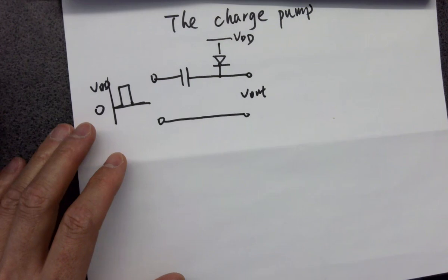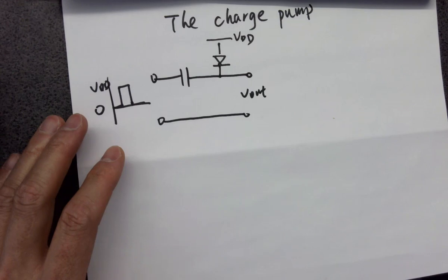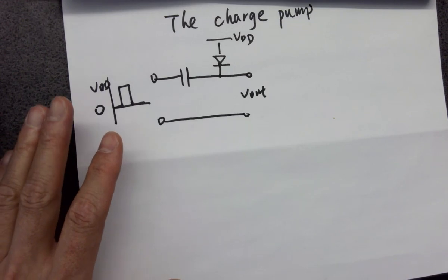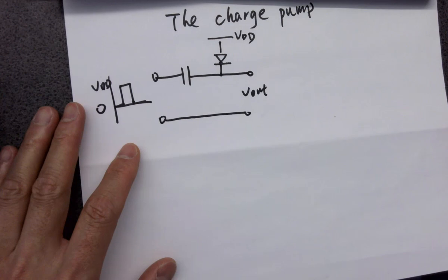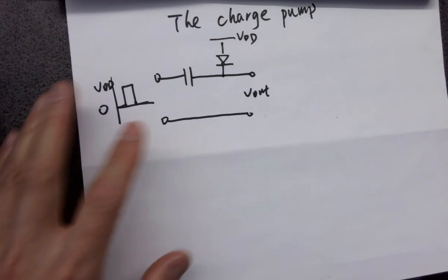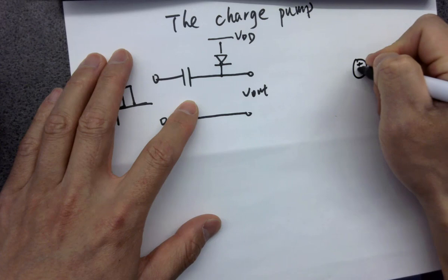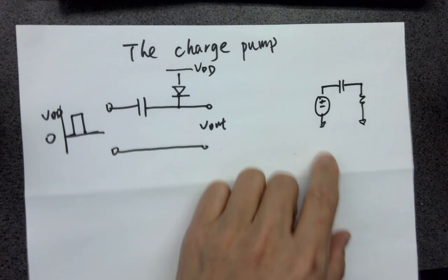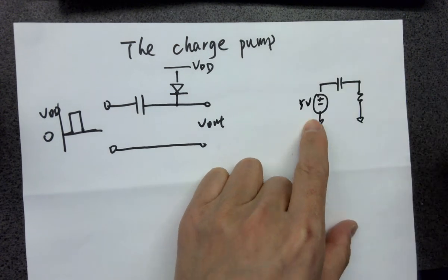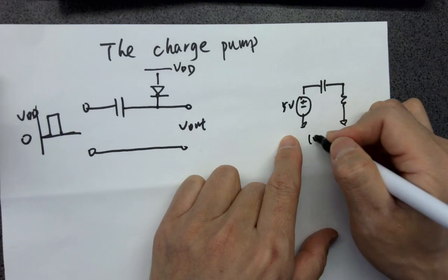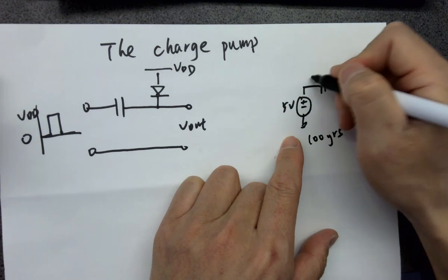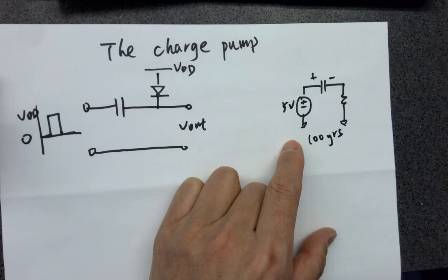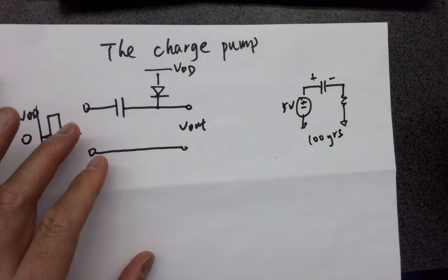You have to have that kind of model in your mind, how a capacitor works for digital circuits. So first, my question is, you have a DC voltage here, like this, 5 volts, and it's been connected like this for 100 years. Is there any current in the circuit? Why? The DC circuit is getting disconnected by the capacitor, right?